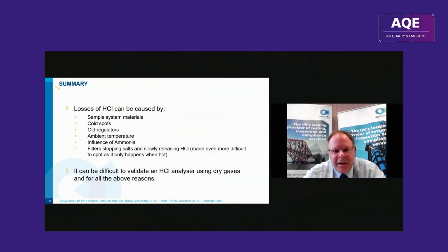And we were seeing about 95% of the mass on the filter was chlorides, which was suggesting that we're seeing ammonium chloride salts collected on the filter, which is why so many of the test runs being done, we're seeing much higher concentrations of particulate. It appeared to be caused by the ammonia and HCl reacting within the stack to form these solid salts.